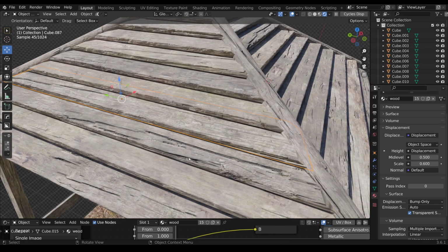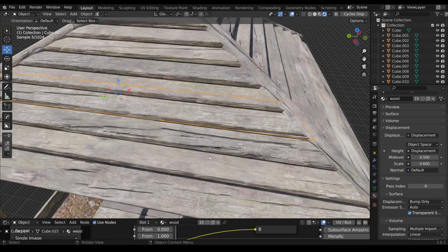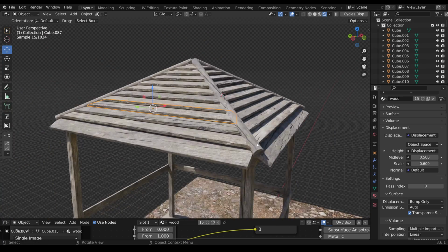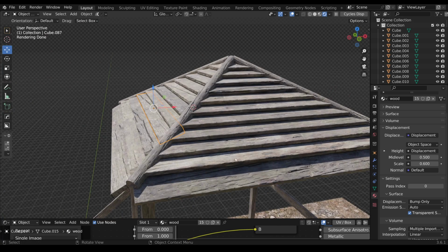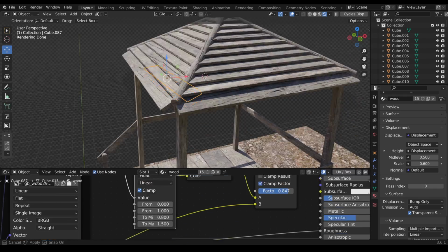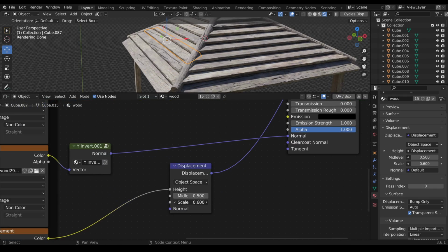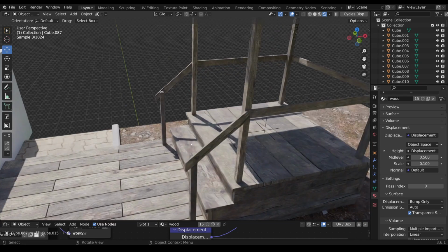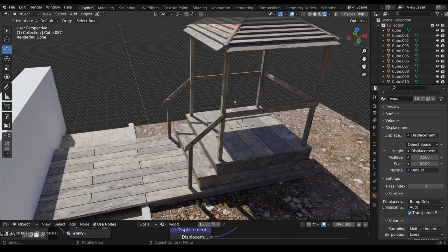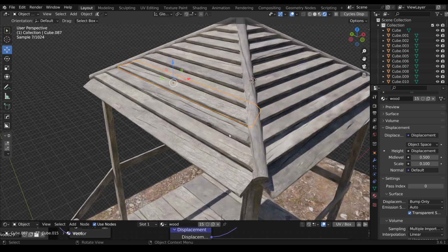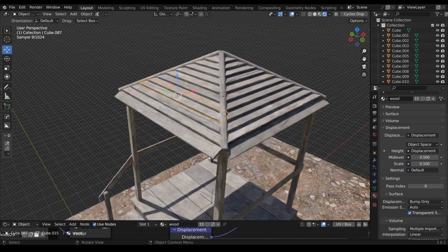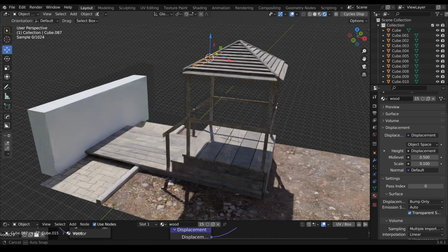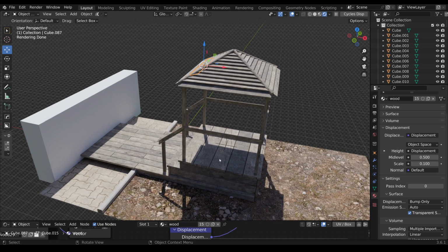As I said, these textures, I'll definitely link to the bump texture. It's absolutely fantastic, top quality. It's such high quality that it's actually too strong in this case. So go into the displacement settings and reduce it significantly, at least to 0.1. I've set it even flatter on my end, and now it looks a bit friendlier. But you can really use this for old wood, for high-quality wood. It's a very high-quality scan.